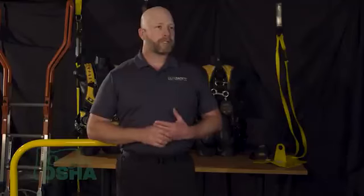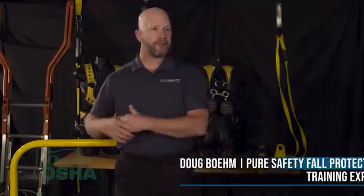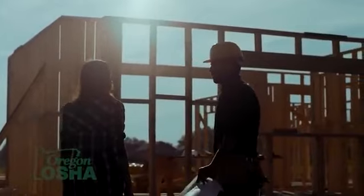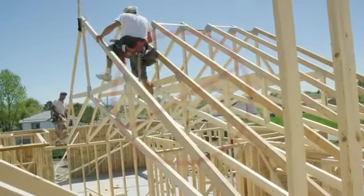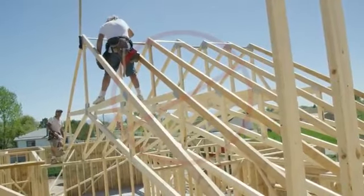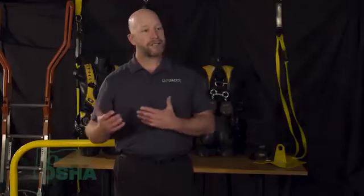The planning process will be another aspect of the fall protection that isn't in the equipment, but in how we plan, how we do the work. Again, changing mindset. In one conversation I had, a gentleman who was flying trusses in said, once we have enough trusses set, it would be dangerous for me to have a guy climb up through the latticework up to the ridge to install an anchor. And I completely agree. You're right, that would be highly dangerous and unacceptable.